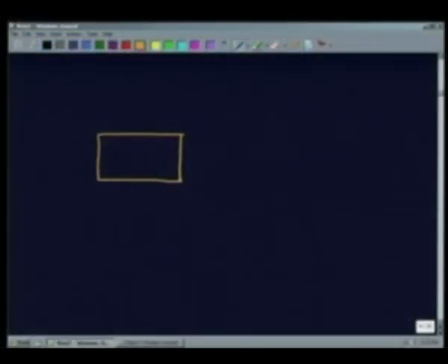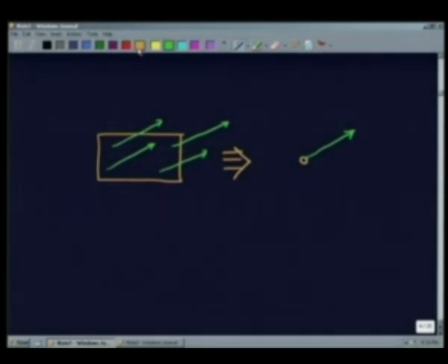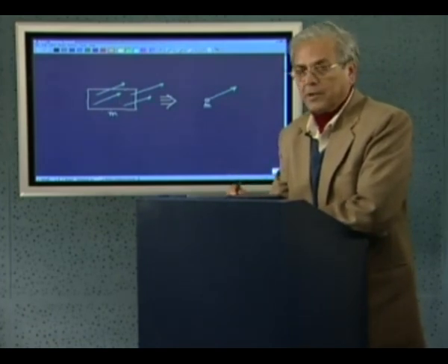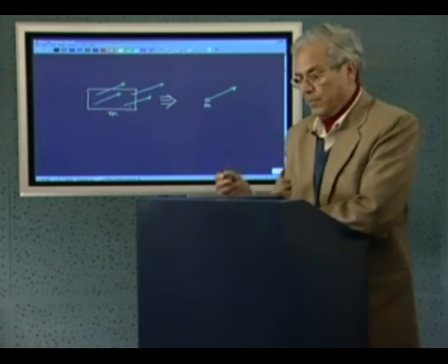It's a rigid body where each point has exactly the same displacement, same velocity, same acceleration. So effectively what we can do then is that this is more or less equivalent to a particle with the same velocity or displacement as this rigid body, but the total mass of this is the same as the mass of this particle. So therefore, in cases of pure translation, a rigid body may be considered to be concentrated in a particle with the same displacement parameters, velocities and acceleration.